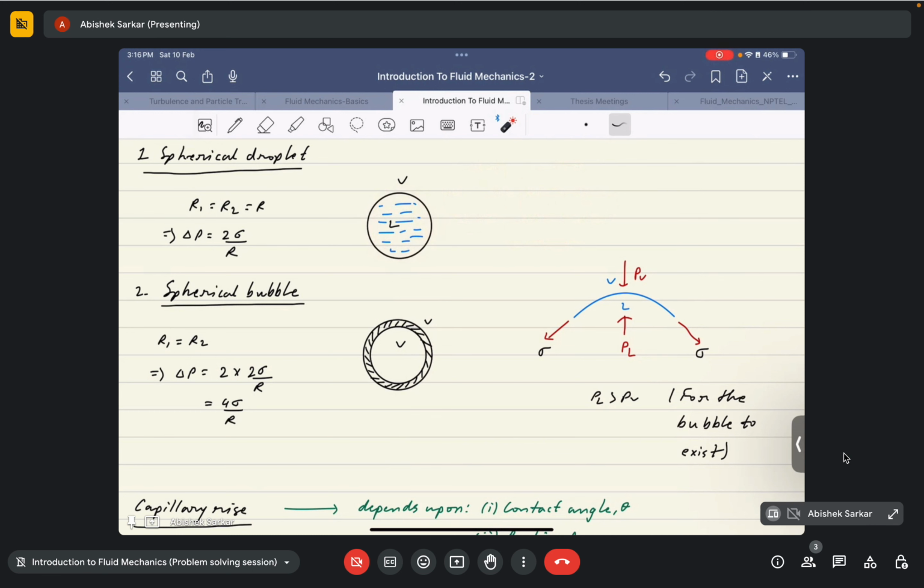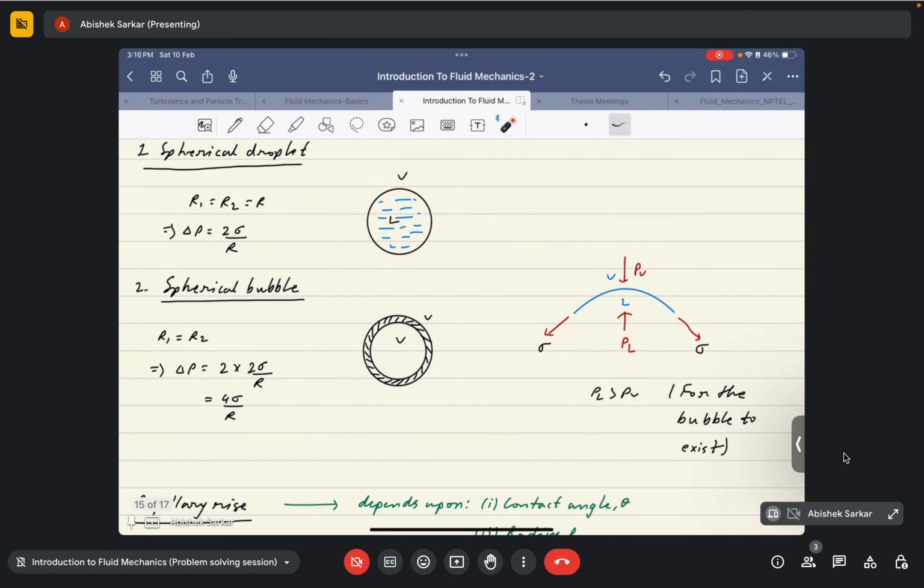Apart from it, there is also an additional force trying to collapse it even further, to have the least possible surface area, right? So there are two forces: first is the outer atmospheric pressure, and also the force trying to compress it even further, right? So there are two forces that the inner pressure has to overcome to maintain its shape. And that's why the inner pressure is always larger than the outer atmospheric pressure.